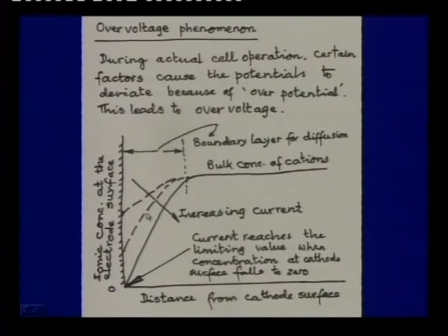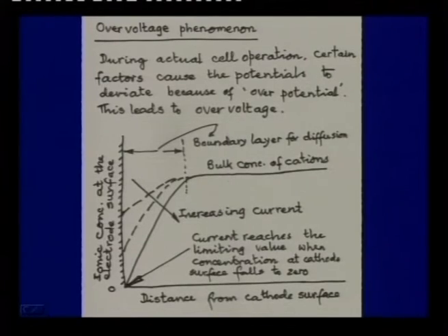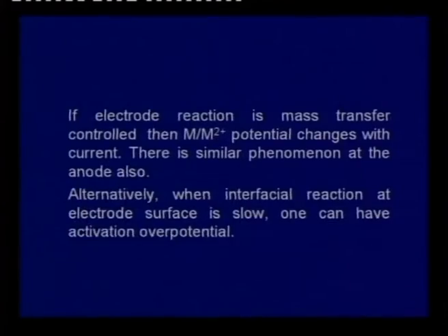Because of concentration over potential, my analysis shows that the potential of the electrode does not change so much, but it sets a limit to production. Now, in some cases the limiting step is not concentration over potential, but activation over potential, which makes it possible to have zinc in zinc electrolysis. But this concept of limiting current density is very important.